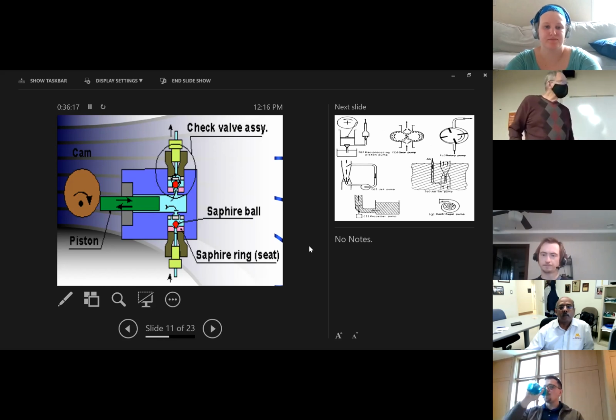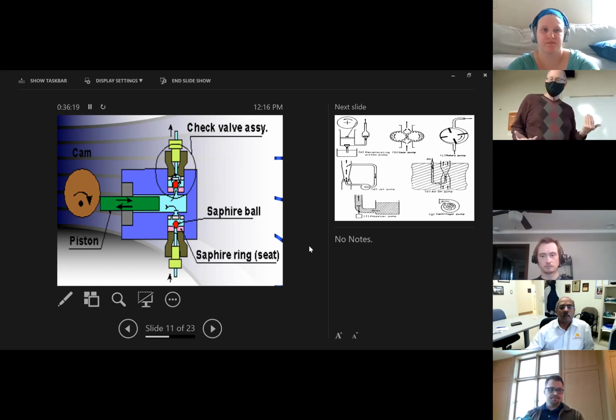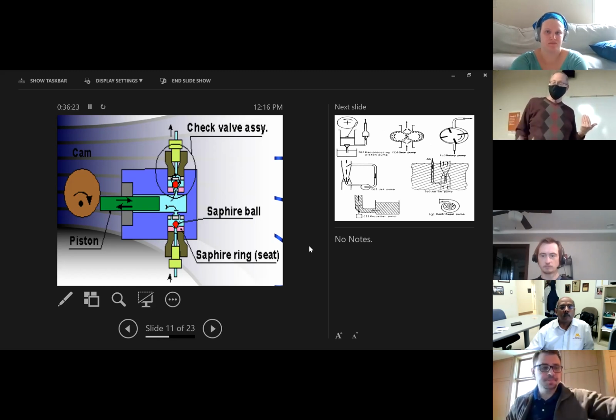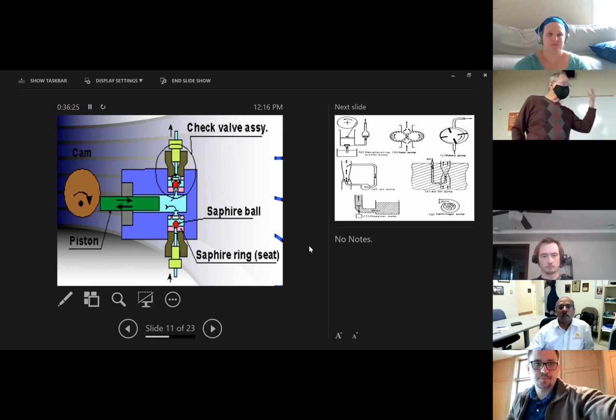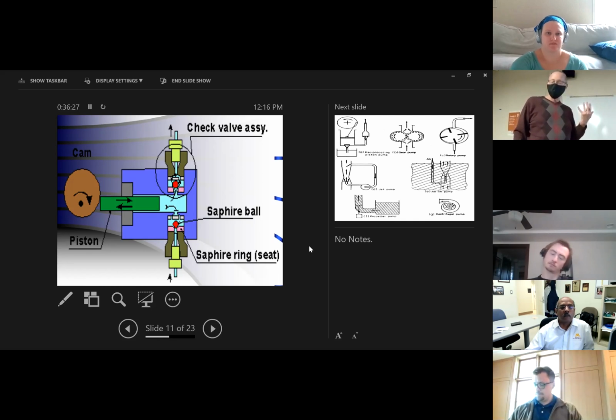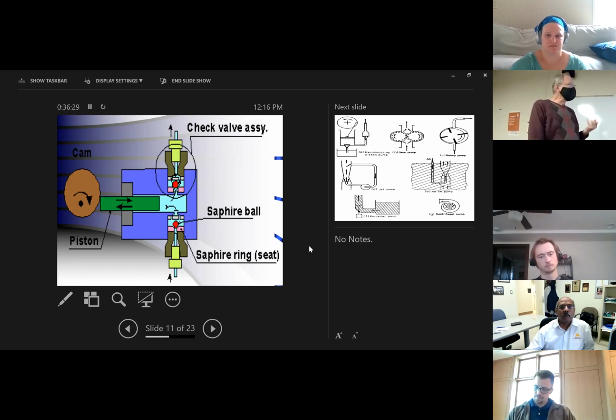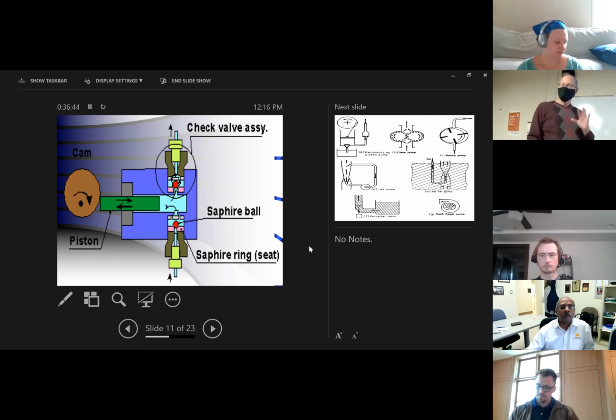The liquid flows from the bottom, whether you're using a big tank where there's a pressure from the tank or a booster pump to get it there, it pops that little bottom ball bearing up and liquid flows in. Piston gets all the way back and it all starts over. And you could see we're putting these in series, 3 or 5 pistons, where you get that evening out, that sine wave effect occurring.